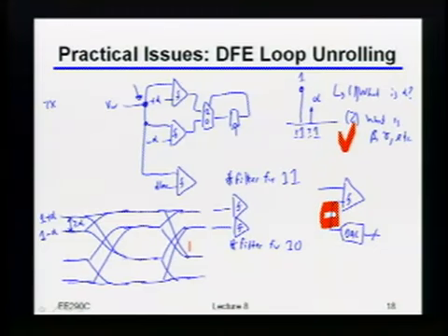I think so. So in other words, if I wanted a threshold at plus alpha or minus alpha, no, I mean at 1 plus alpha and 1 minus alpha. Right, but so all I can do, well, maybe I misunderstood what you're saying. If I find 1 plus alpha, if I don't know the DAC transfer characteristic perfectly, that doesn't tell me where alpha actually is.